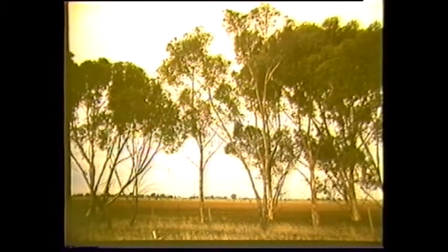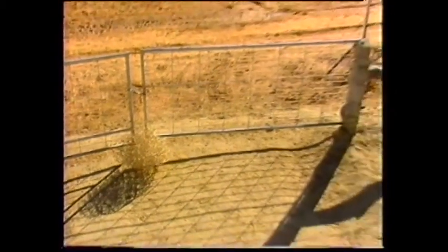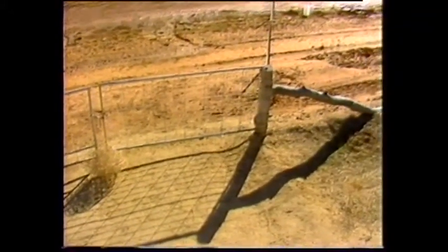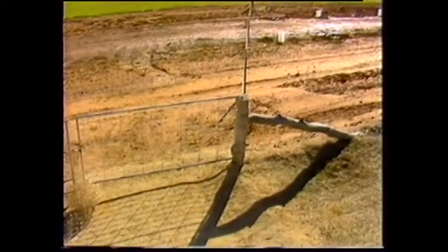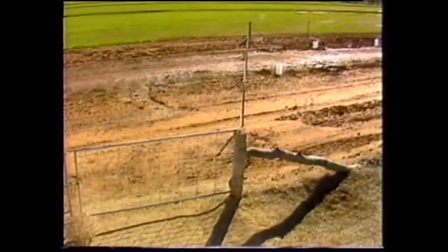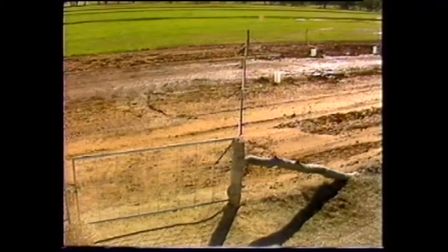This is not to say that big gaping holes in windbreaks are useful. Rather, the opposite applies, with these spaces actually focusing wind energy, creating a tunnel effect, which may even increase areas of wind erosion. If you must have a gap in a windbreak, such as a stock entrance, this should be designed to minimise deleterious effects, such as the case in this windbreak. The gateway is tunnel-shaped to distribute the wind focusing effect over a wider area and hence decrease its intensity. The entrance is also orientated such that it is not in line with the prevailing winds, but rather at an angle to it.